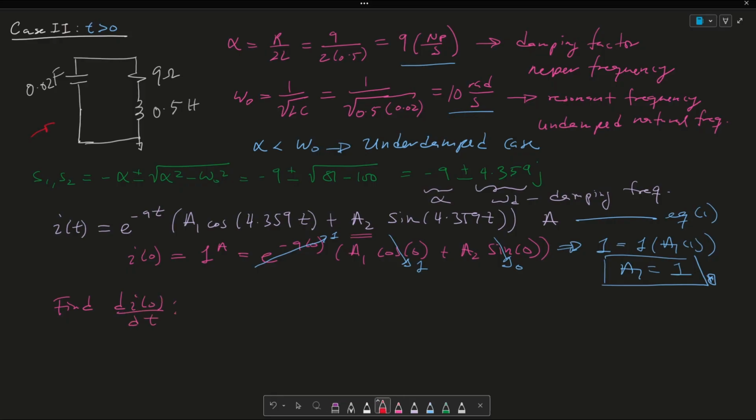In order to do that, let me take this circuit here and say that I have a current i flowing through it, and there's a plus minus here, there's a plus minus here, but here there's a plus minus. And again, remember the v of t from our previous slide that flowed through my capacitor and my resistor. And let me go ahead and write a KVL in this loop. So I can say that this is minus VC plus VR plus VL is equated to 0.